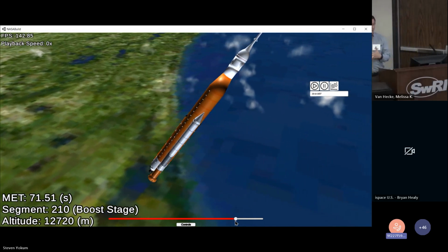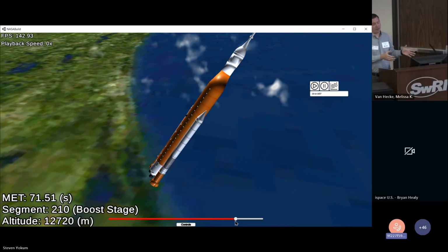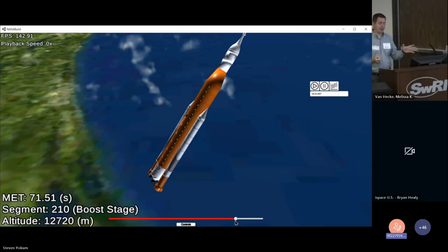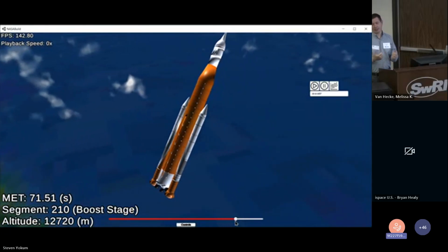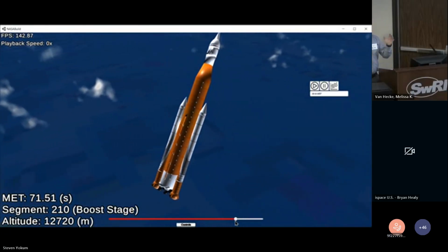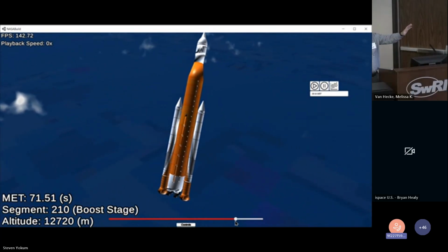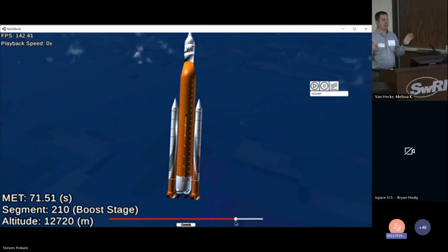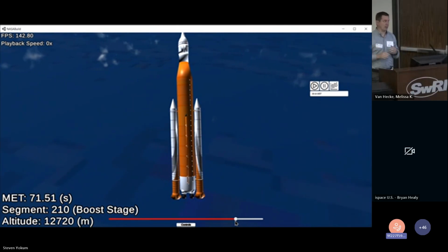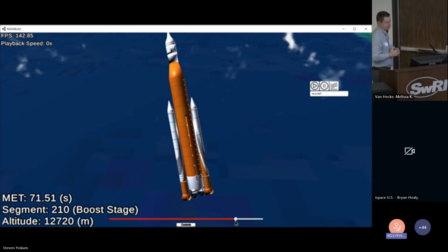And what would I do if I did that again? I would make the effort. People tested the triplex at one point, but they don't do that anymore because it's well established. We'd make the effort to run simplex and get rid of the need for the triplex. I'd still like to go simplex and get more performance back, but the components within that vehicle talk to 1553 buses that connect to only certain flight computers, so getting rid of the full flight computer setup has some complications. But I would put more effort into getting to simplex on the back end.